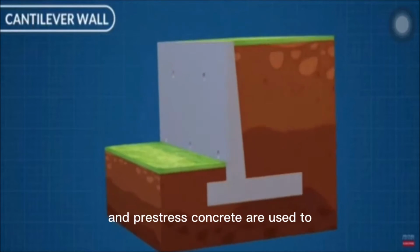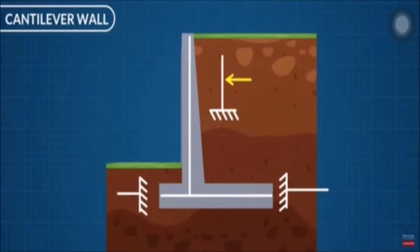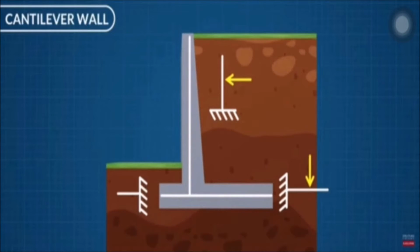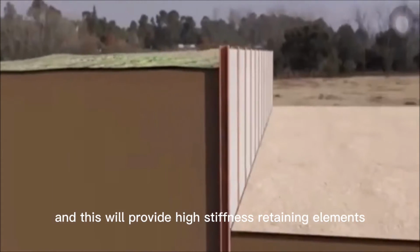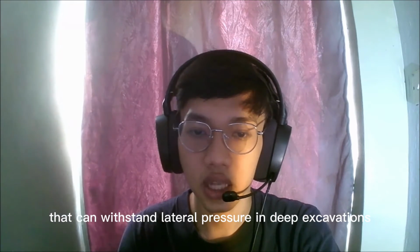Next, we have the cantilever retaining wall. Reinforced concrete, precast concrete, and pre-stressed concrete are used to construct this common retaining wall. This retaining wall can be built on site or prefabricated off site, which we call precast. The next retaining wall is the pile retaining wall. These walls are built by driving reinforced concrete piles next to one another. This wall provides high-stiffness retaining elements that can withstand lateral pressure in deep excavation.